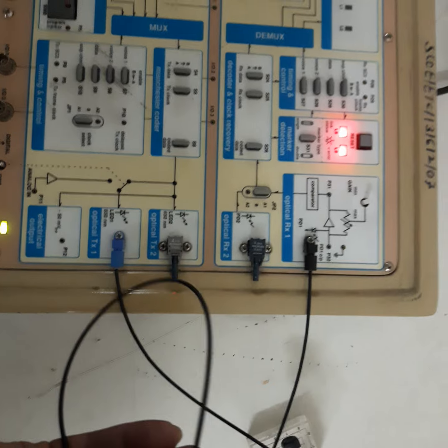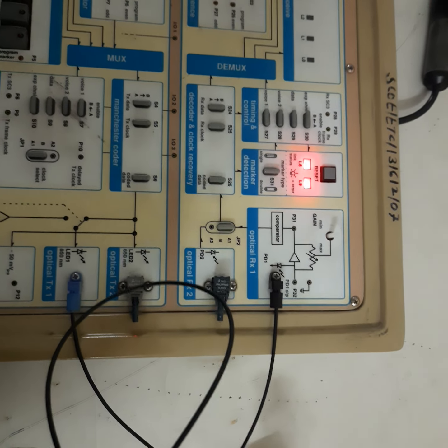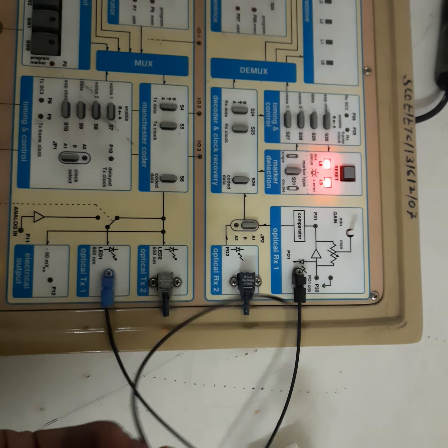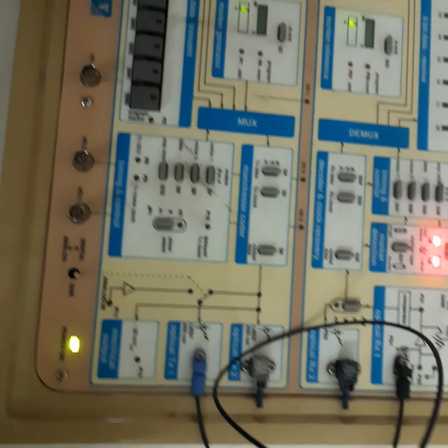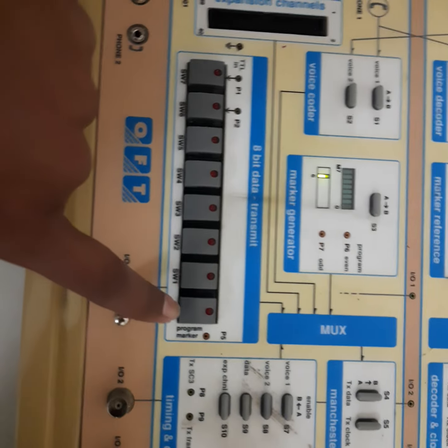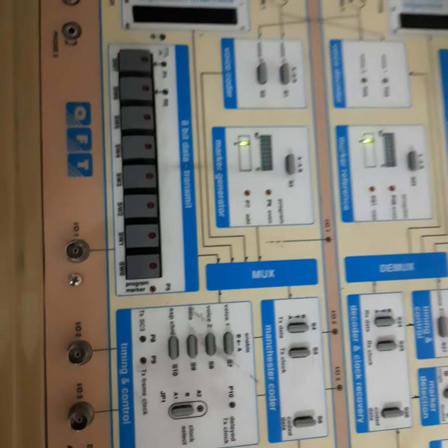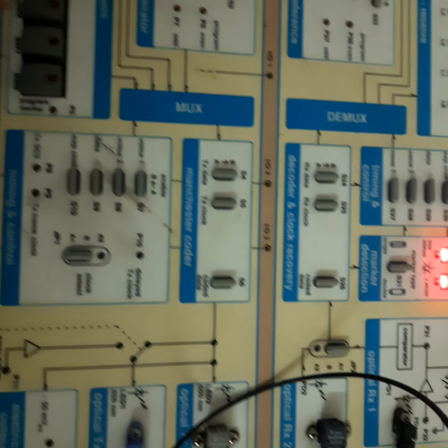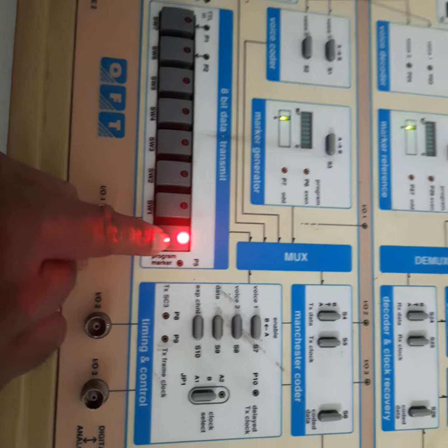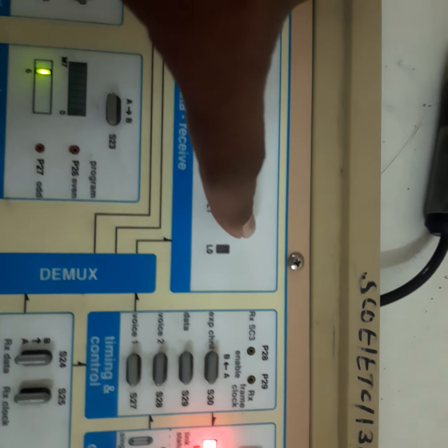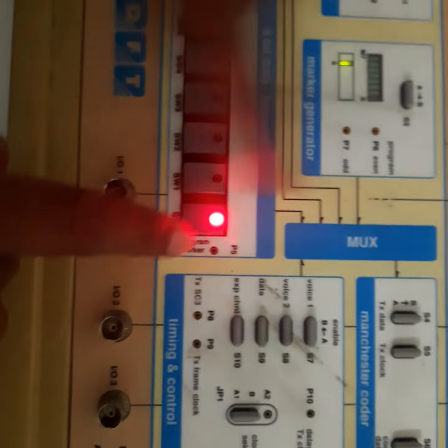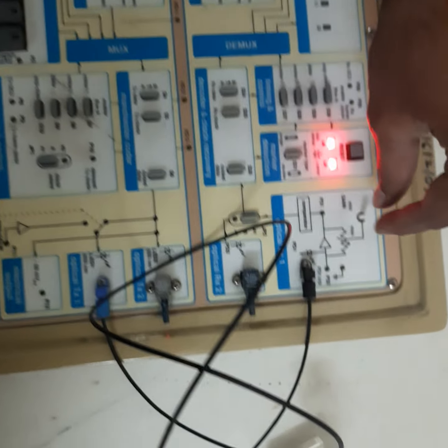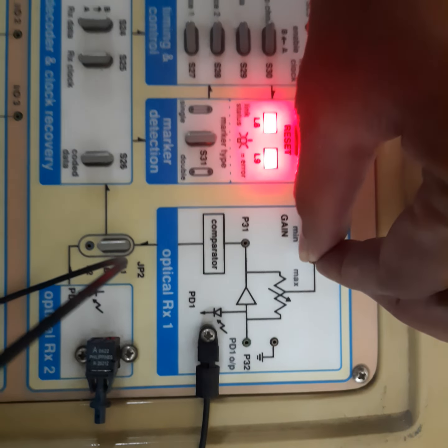So how do we ensure that the link is established between the transmitter and receiver? There is a simple procedure for that, and it is common for almost all practicals, around 4 to 5 practicals. On this side we have 8 switches, SW0 to SW7. When we connect the fiber between LED1 and PD1, how do we ensure the link is established? Suppose I press SW0, then the corresponding L0 should glow. In this case SW0 is on but L0 is not on, so the link is not established. For establishing the link, there is a gain control knob provided here, so you can just vary that gain control knob.